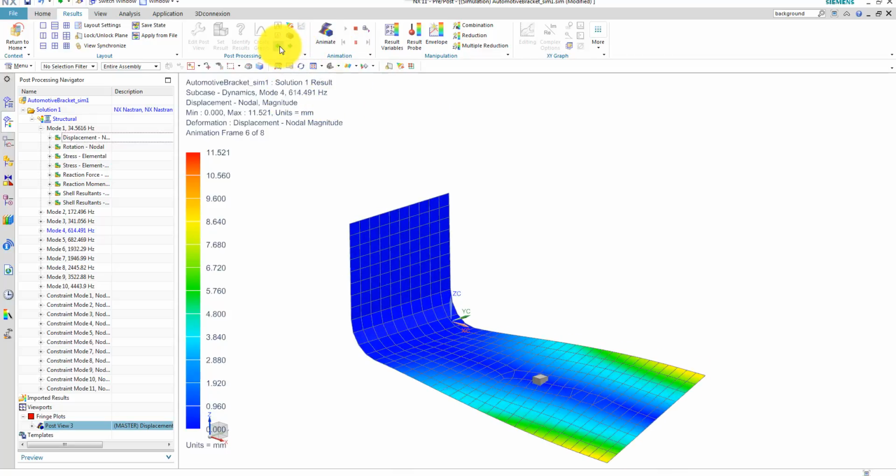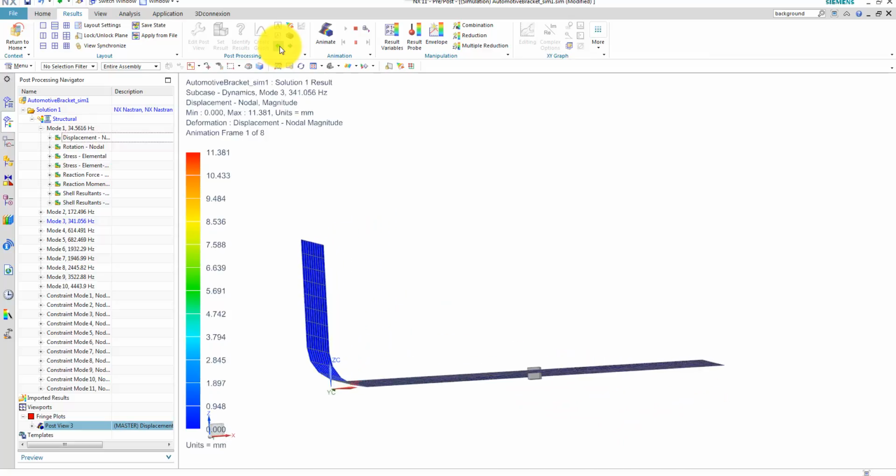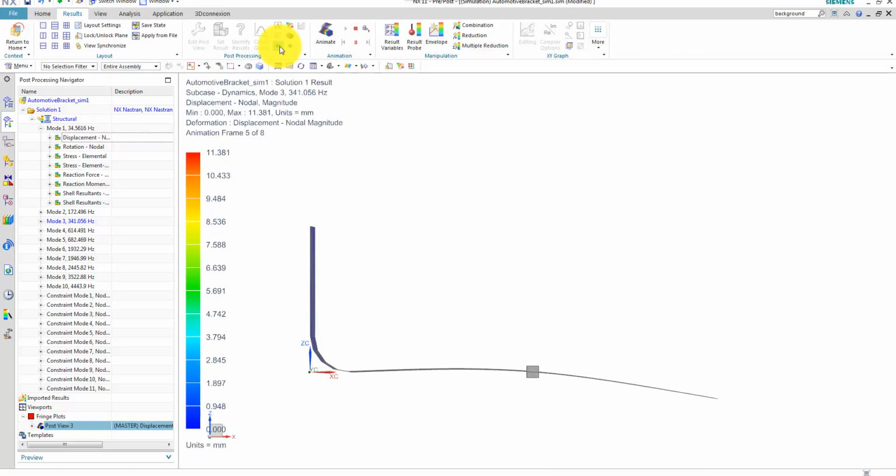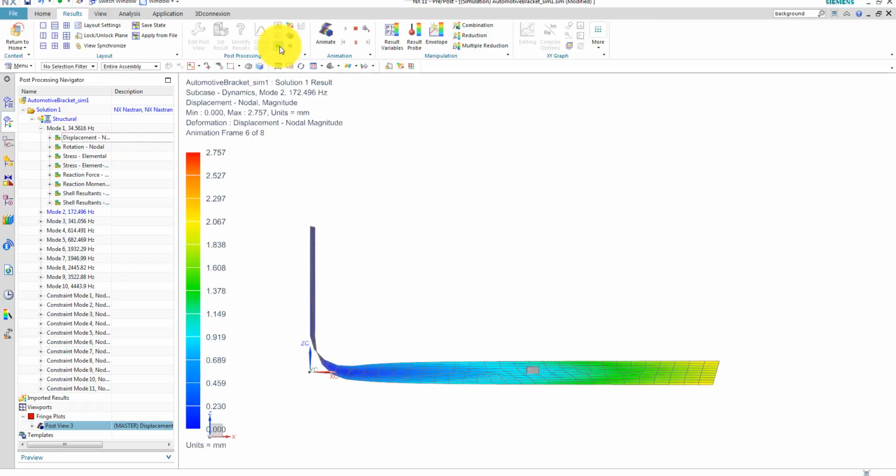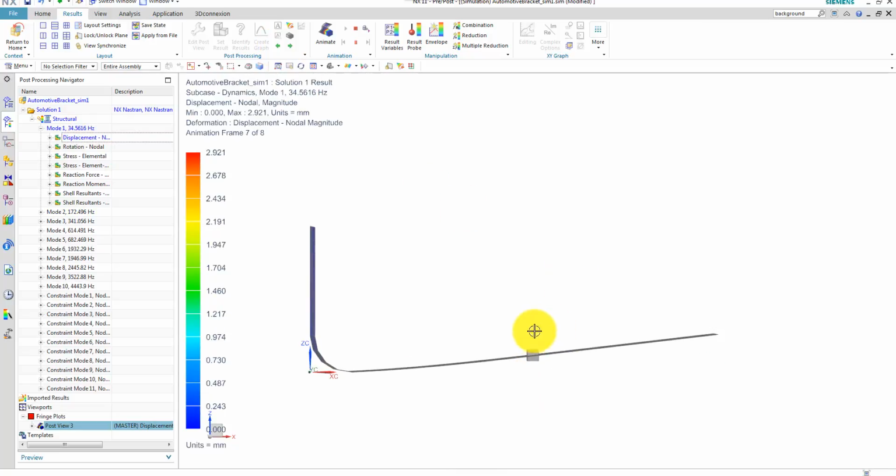But if you step back, we can see that this mode, you can tell it slightly contributes to this set displacement of the structure. It doesn't move the additional mass much, but it moves the other distributed mass in the shell elements a bit, not too much. Let's check the second mode. Well, it doesn't contribute much to the set deformation of the structure, a little bit perhaps, but then this one, it contributes a lot to the vertical displacement of the additional mass and also the shell elements.